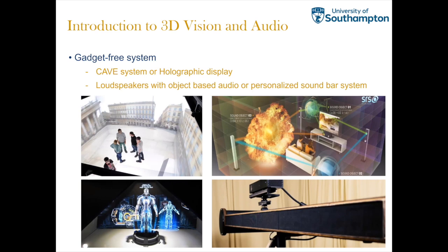And also there's some kind of personalized sound bar system, using some speaker arrays. Normally the problem of sound is that once you play the sound, it propagates everywhere and then reflects, is absorbed, and scattered everywhere. So at the listener position, your sound is just a mixture of reflections and scattered, messed up signal.